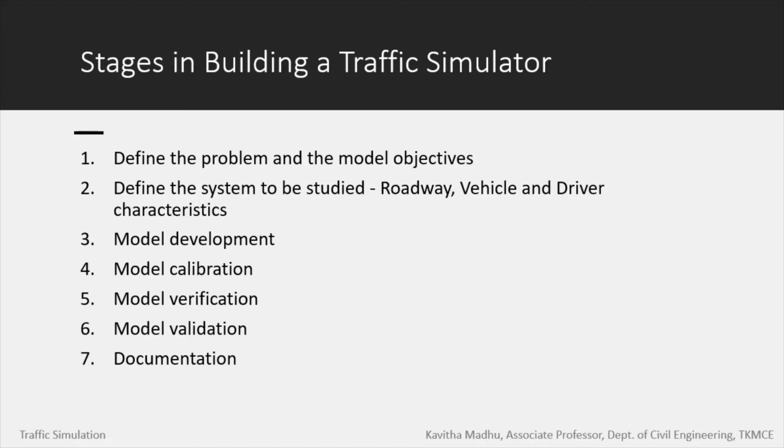Then comes the validation. Validation means we have created the model and we need to see how much it is matching with the field data. So we have some performance measures, and we will be collecting some performance measures from the field. Say this is the speed with which vehicles are traveling, and we simulate something and get a speed out of that. Then we validate how much is the difference in the speed, or we compare the volume between the simulated and the field data, and we see how much error is happening there. Accordingly we need to minimize the error and validate our model.